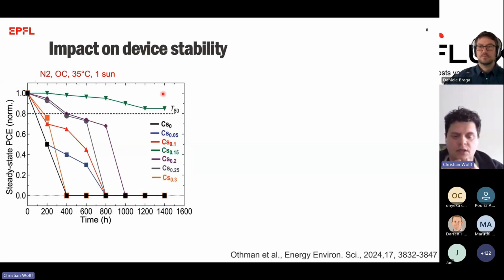You take your cell, place it under a solar simulator with or without temperature control, take it out and measure it in several time intervals. This is nice in two ways. For one, it's a relatively simple setup. You just need a lamp, if you are being honest, in addition to what you already have.